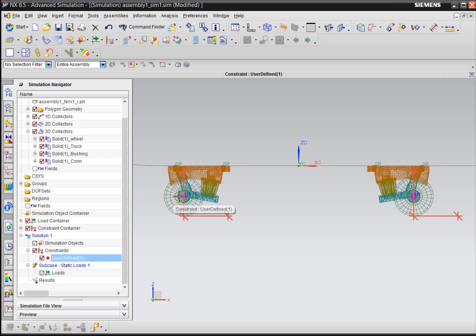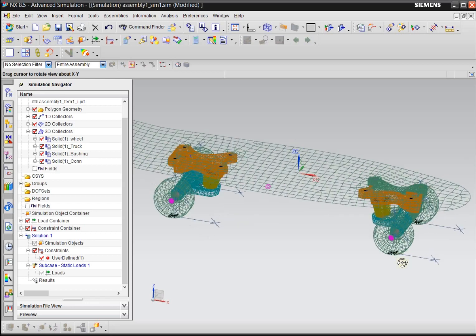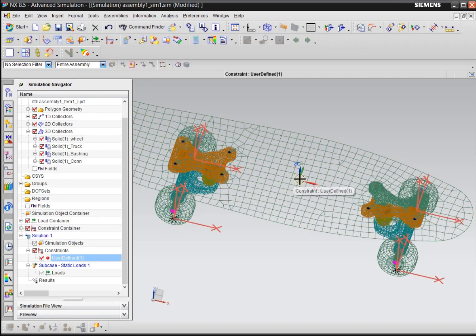So this is actually not a stable structure, that's why it will roll. If you only grab these two and the bottom nodes, it's like you have a hinge here, a hinge here. The top bar will move left and right. So for this simulation, we need to grab the center node here to prevent this from happening.